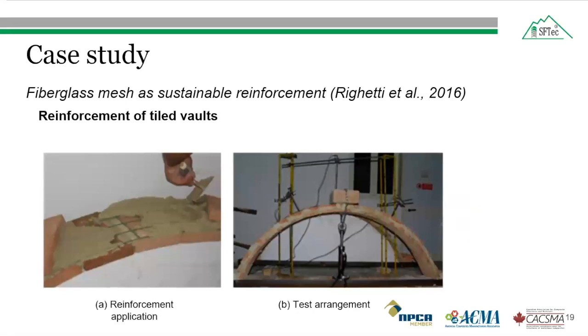So the vaulting system often needs to be retrofitted to resist both horizontal and vertical load. In this investigation, 17 test specimens were constructed with a segmental arch shape, using methods typical of those employed for many historic bridges.